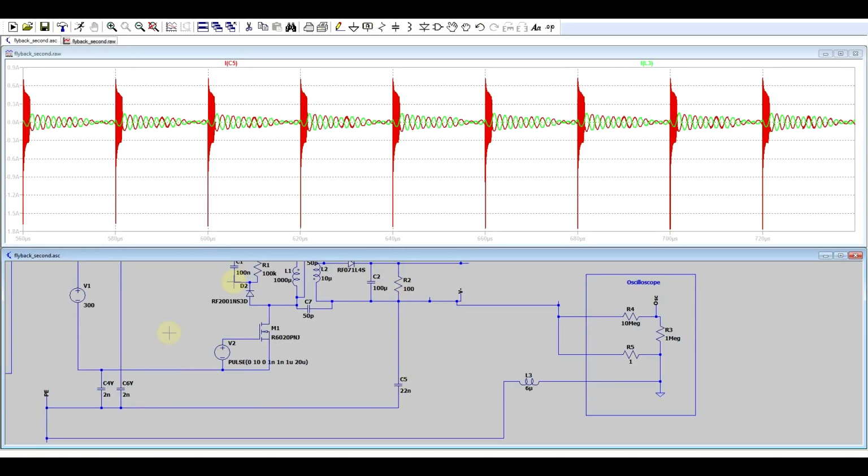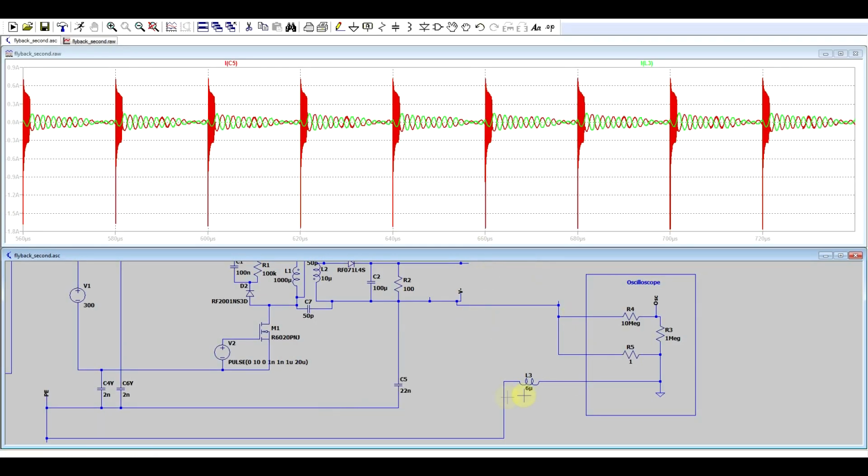The root of the problem is that the supply is noisy and that the initial capacitors which were placed in there to keep the noise inside the supply are not doing a very good job. Basically, when I connect my oscilloscope through the protected earth, the impedance of the connection has a close value to the impedance of the output capacitor, so the capacitor from the output to the protected earth inside the supply.